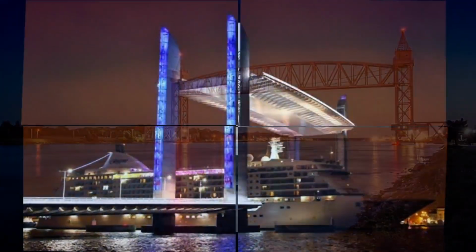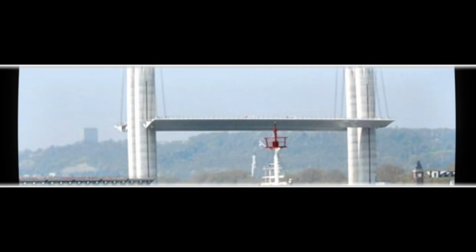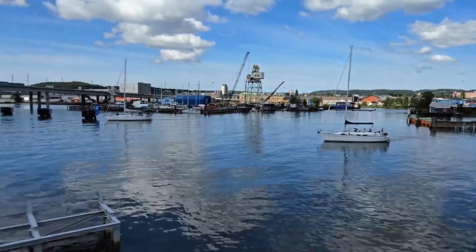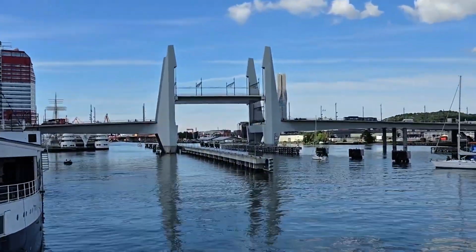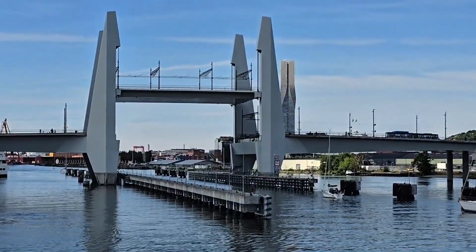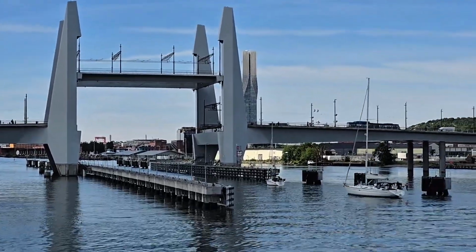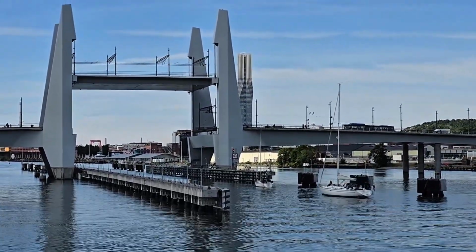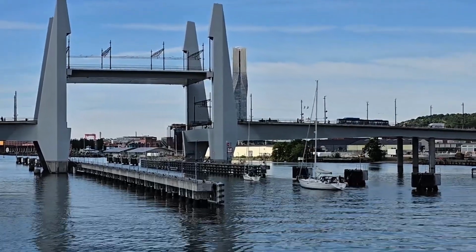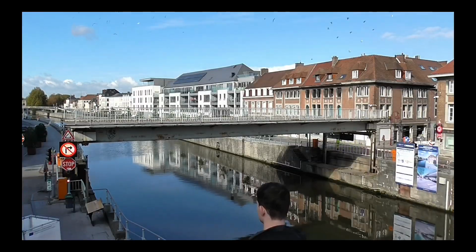Table bridge. A table bridge, also known as a lift table bridge, works much like a vertical lift bridge, but usually on a smaller scale. The roadway deck is raised vertically on hydraulic or mechanical lifts, resembling a table being elevated. They are most often used for canals, small rivers, or pedestrian crossings where moderate clearance is sufficient.